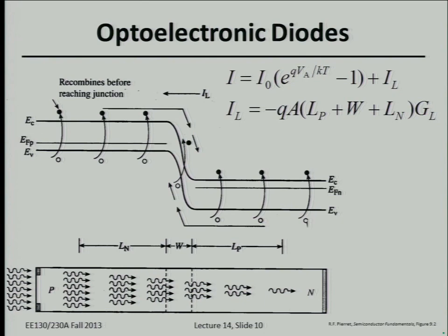The absorption length, or the depth to which light is absorbed in various materials, actually depends on the wavelength. In silicon, within the visible light spectrum, it can be microns of depth. So you'll have photons reaching the P side, the depletion region, and the N side. So let's just assume that we have lots of light shining on all regions of the PN junction diode, so that electron-hole pairs are generated in all regions.